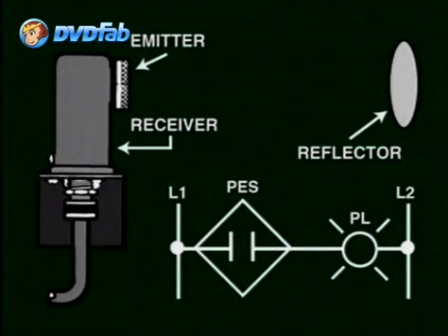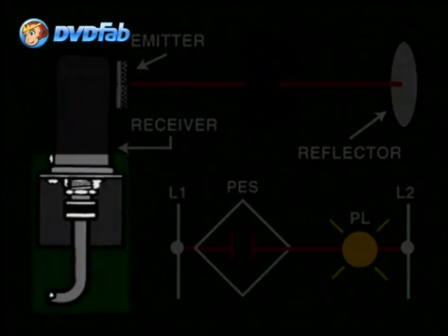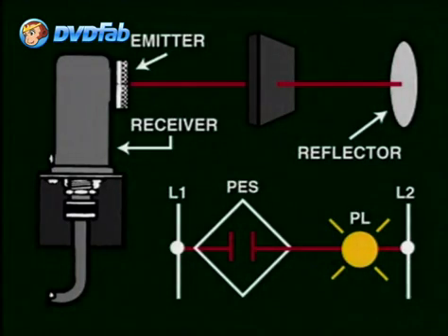The retroreflective scan sends a scan that is reflected back to the switch. When the beam is broken, the switch is activated. One advantage of this type is that it only requires the wiring of one single unit, while the alignment of the reflector may be non-critical.